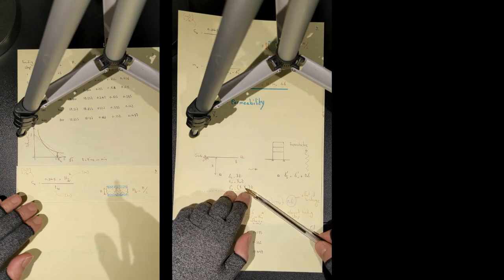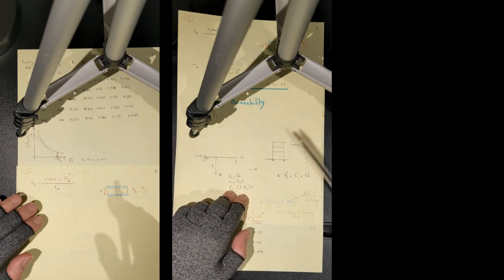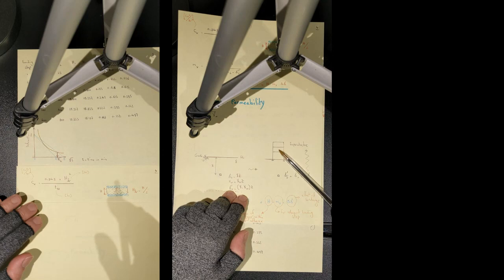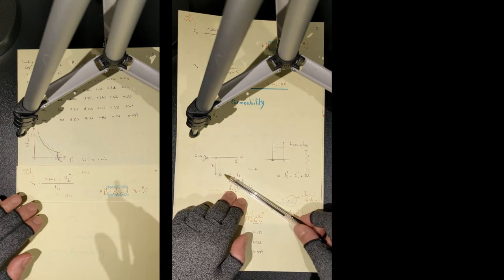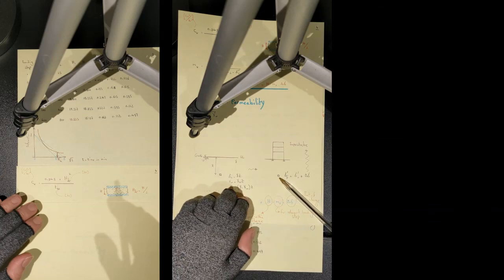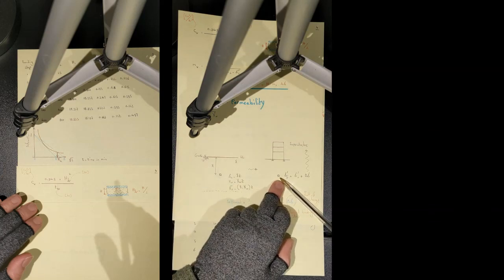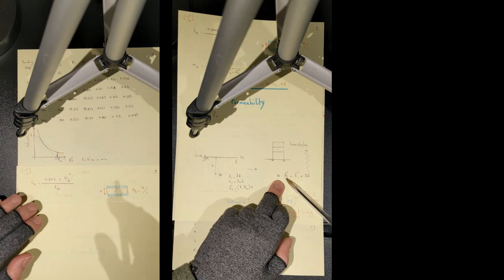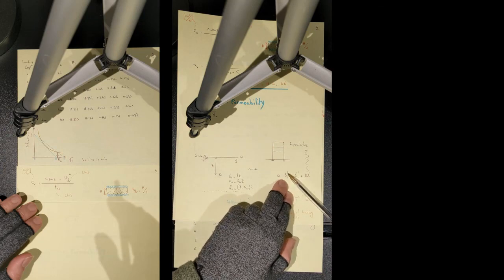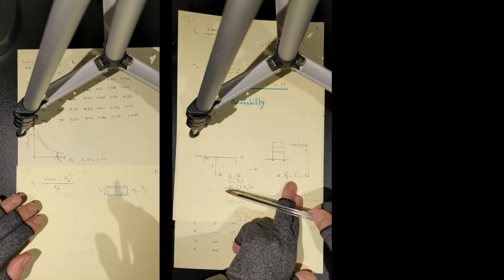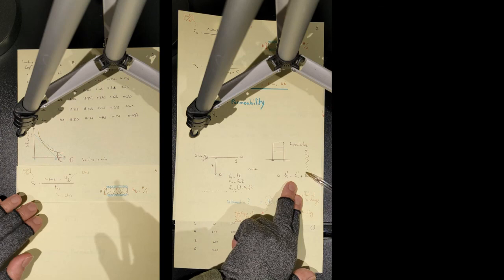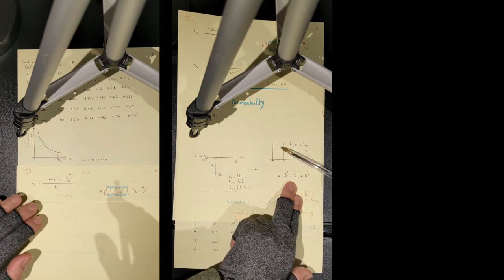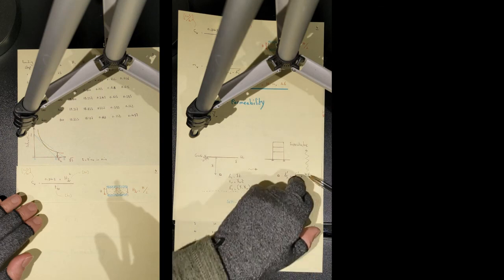You're planning to build a two-story building. That is your superstructure, and this is your point of interest in the middle of the clay layer. And you know that after completion of building, your final effective stress will be equal to the original effective stress plus, let's be very conservative, 100% of the weight of the superstructure. Simples.